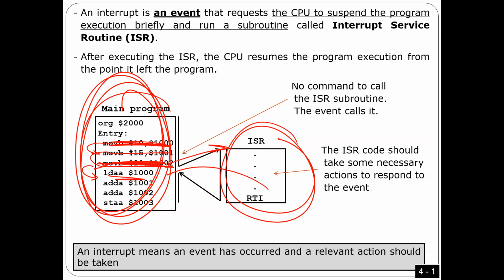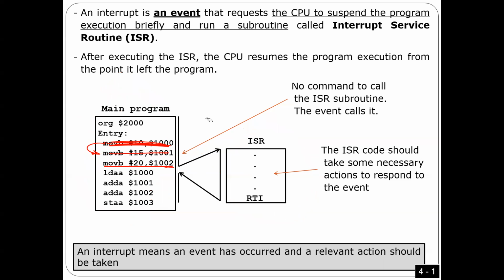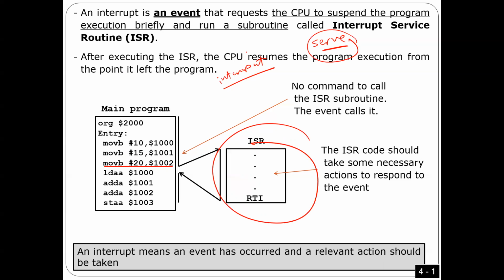So what do you mean? This is the expression, the term we are using. And if you have an interrupt, when I say I serve the interrupt, what does it mean? Serve the interrupt means I'm going to execute the subroutine of this interrupt. When I execute the subroutine of this interrupt, that's what I mean by we serve the interrupt.